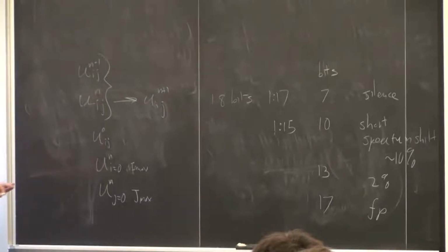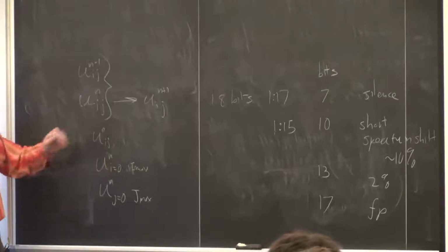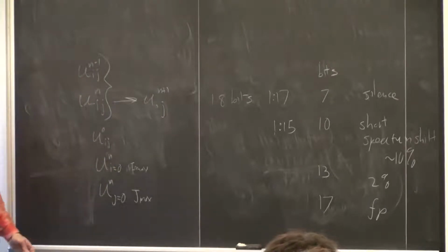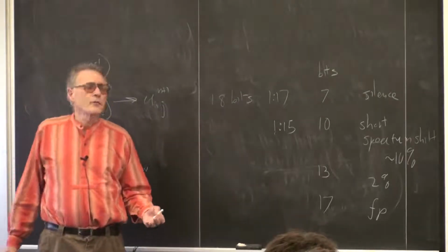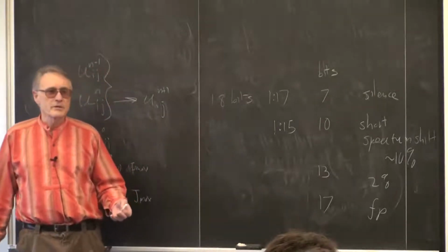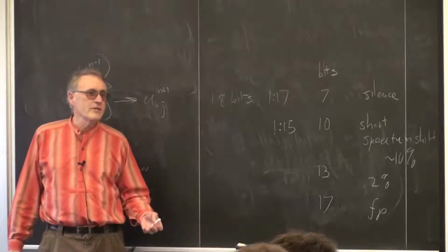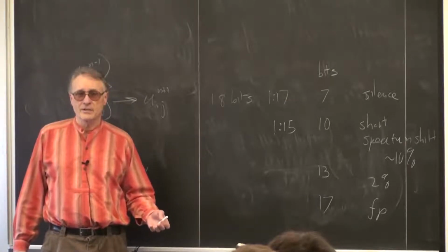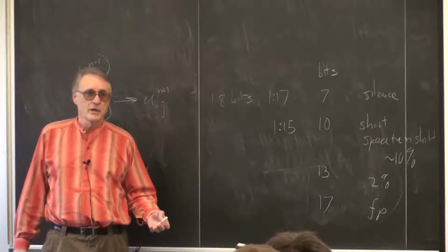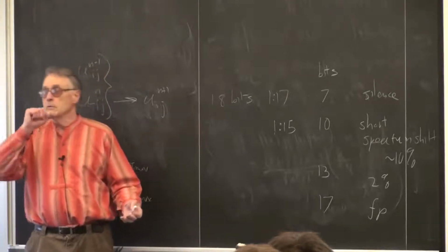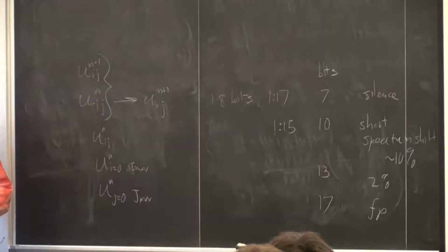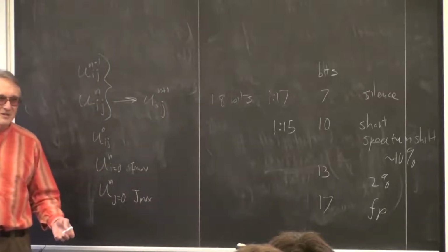So you're going to evolve this equation according to the evolution equation that we talked about last time, carrying about 18 bits. You can carry more if you want. You get a better sound out if you carried 27 bits, which is the next obvious size for the multiplier, because a multiplier will do a 27 by 27 multiply. That halves the number of available multipliers, however.